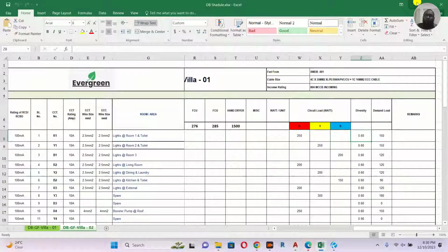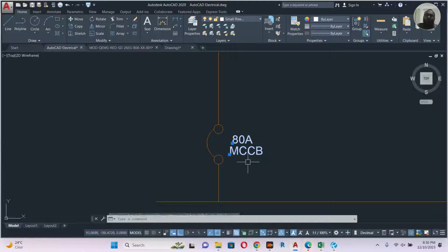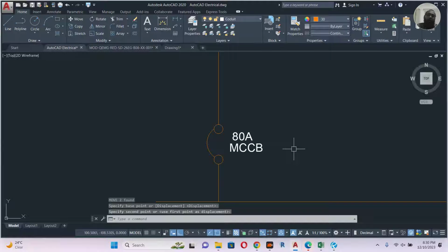What will happen is, instead of overload, before the DB, the SMDB will be off. Let's say if the overload came, there would be more heat and it would catch fire. But if the DB can handle 100 ampere, the fire accident will happen if the load reaches more than 100 ampere. So before reaching 100 ampere, the SMDB is already at 80, so it will trip. So any fire problem happening in the house will be reduced.